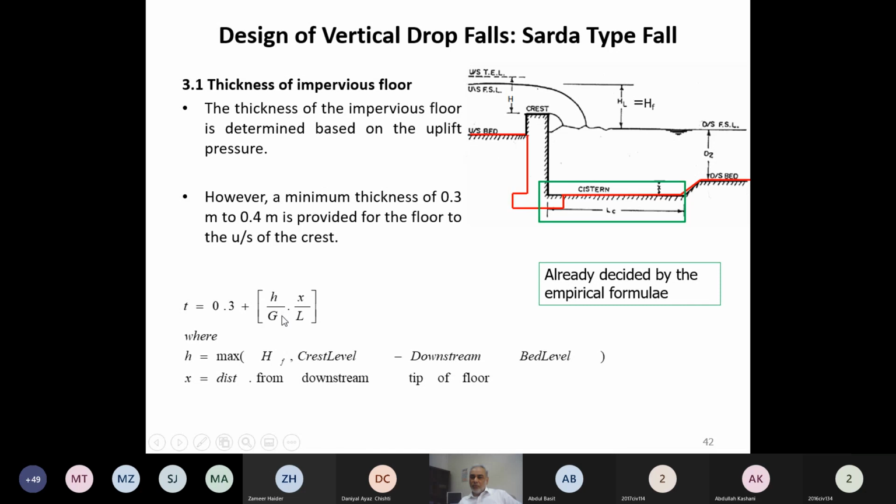That will come from the unit weight of that material. Got it? So specific gravity multiplied by the unit weight of the water will give us the unit weight of that material. Then the unit weight of that material multiplied by the same area of 1 meter square will give you the weight of that material. So they are balancing each other.